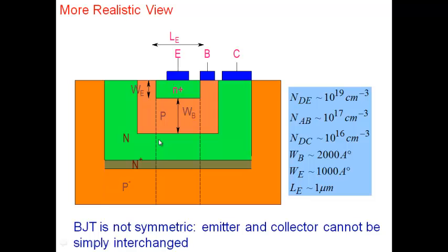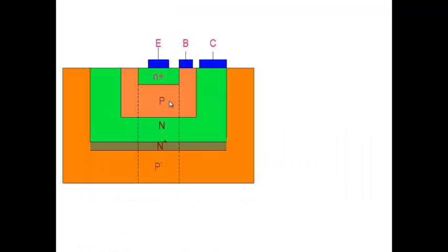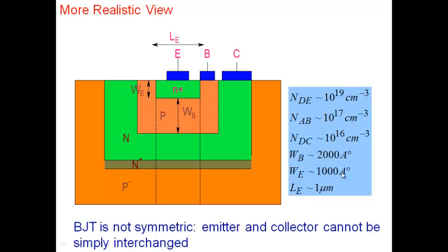If you're wondering, why do I have P minus? Why not just start with a silicon, which is N plus and N, and then just make the transistor? The reason why we have this P minus region here is that you're not making one transistor. When I'm making a circuit, let's say the circuit consists of, as an example, 2 NPN transistors and some resistor and things like that. Now, the 2 NPN transistors, I have to make on the same silicon substrate.